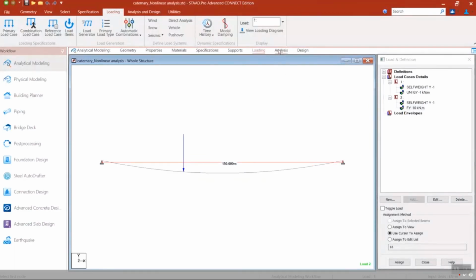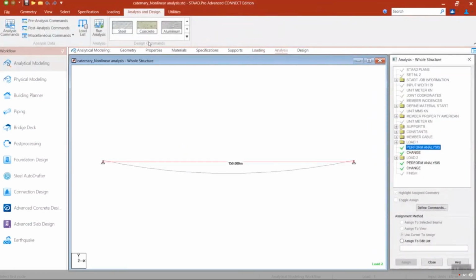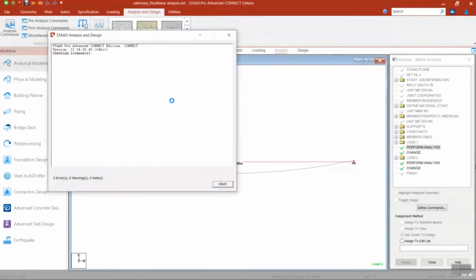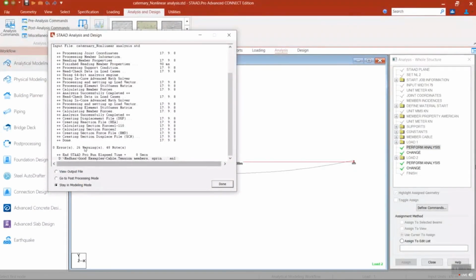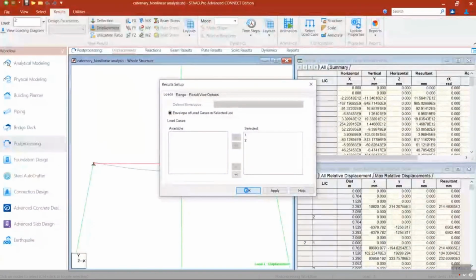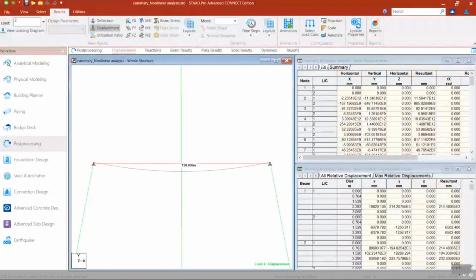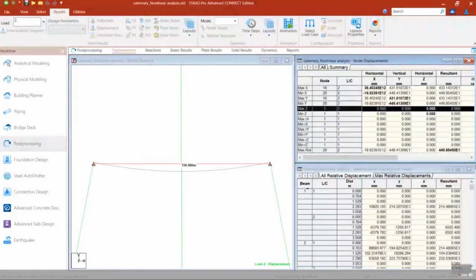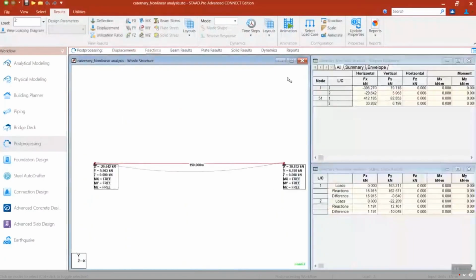You can see the deflection diagram is all haywire, and the deflections are in kilometers. The static check doesn't match: the total applied load and the reactions differ a lot. The output file will be full of zero stiffness warnings, as well as instability warnings.